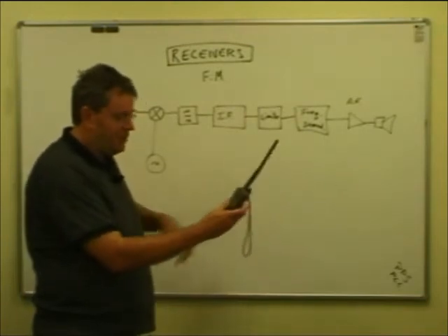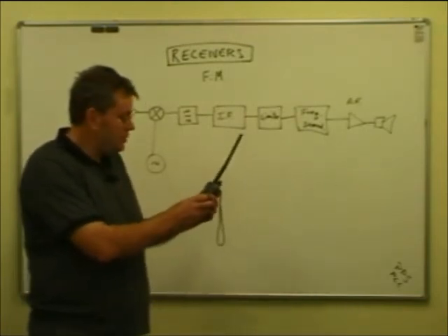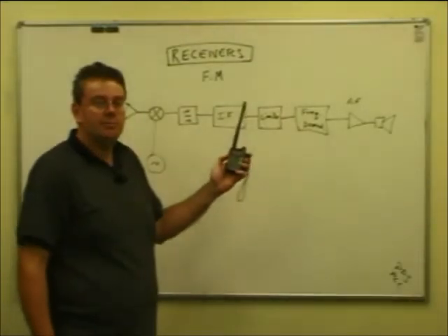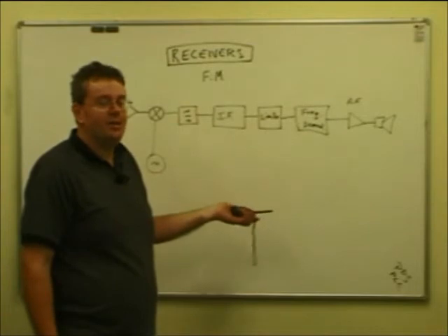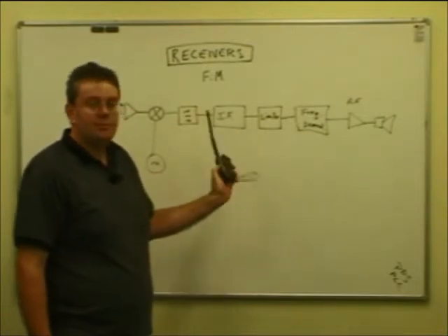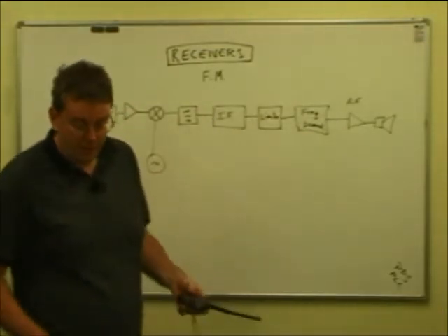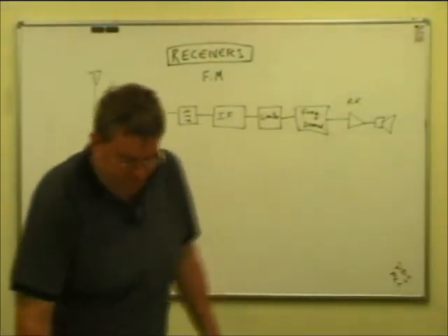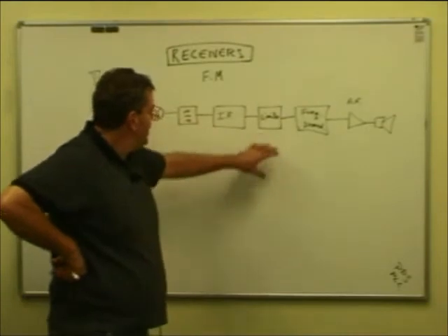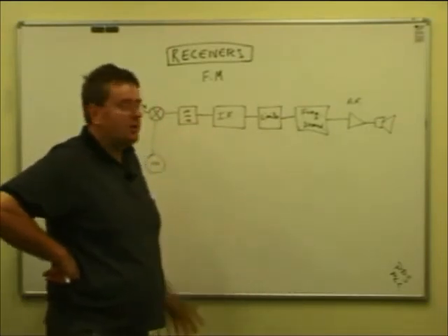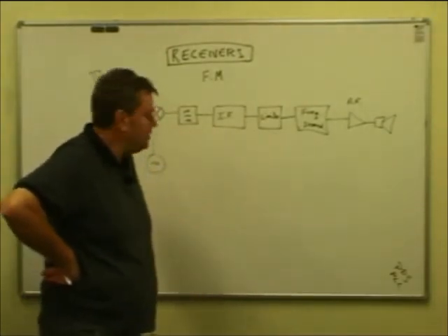So we'll just power up this receiver, but it's kept silenced by a squelch. So there you are. When I push the button there, it just turns the silencing system off. And that's what FM receivers sound like when nothing's going into them. They generate all that noise. For the reason just explained, they're amplifying the heck out of nothing, out of the noise coming through anyway, and then you just hear that horrible rushing noise.